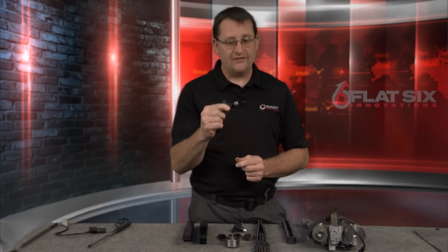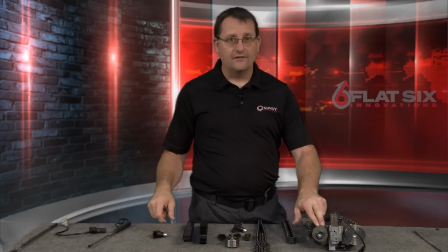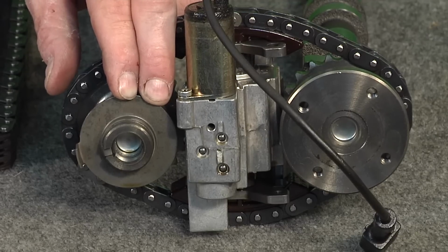But again, that code says camshaft position sensor out of range. Usually that's not the sensor. That's the fact that the camshaft position is further out in respect to the crankshaft position than the ECU has for an allowable. It sets that diagnostic trouble code and it alerts you that you have a problem. Now you have to do something about it. So much like I did a little earlier in this video on the 3-chain topic, I'm going to touch on a couple of other things that can also be considerations for out of specification camshaft deviations for the 5-chain.